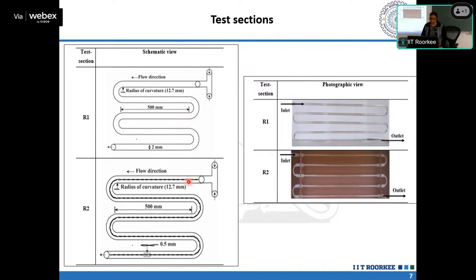So we thought maybe injecting a twisted stainless steel wire inside this serpentine channel may be helpful. Let us try that and see what happens to the reaction. We twisted two very thin stainless steel wires inside this reactor so that we get some undulation and it forms something like an annulus. This is why the contact angle with respect to stainless steel is also mentioned.